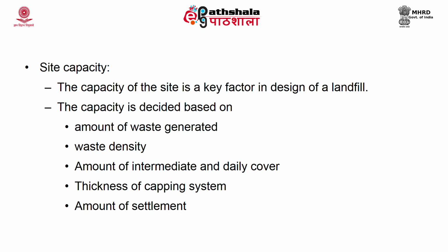Then the amount of intermediate or daily cover. This you will understand much better when we discuss the structure of a landfill. The waste that is generated every day, for example, the amount of waste that is generated for today, will be placed in a cell. At the end of the day, a thin layer of soil is used to cover the waste material. This will help avoid the loose material from flying away, and also small rodents burrowing inside. So, that is important. The amount of intermediate and daily cover also determines your site capacity.